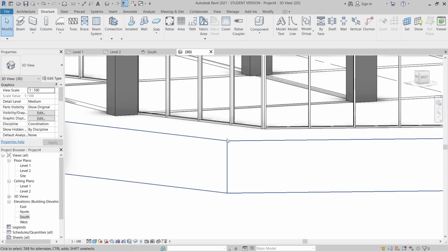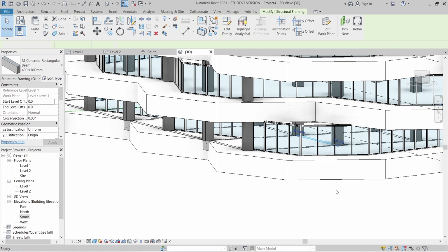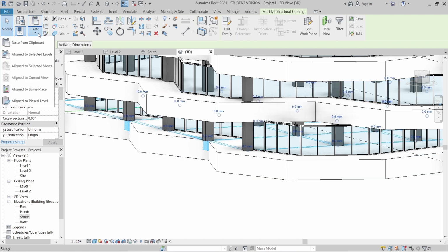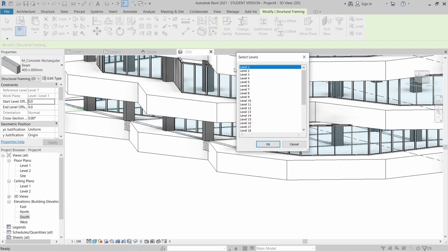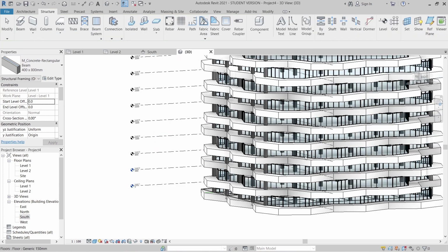Basically our beam is here, as you can see. So you can select all here, then copy as well. You can just select SA for select all element, then simply go to copy to clipboard and paste and align to level. Then simply start from level 2 until the rest here is follow same instruction for our column there.